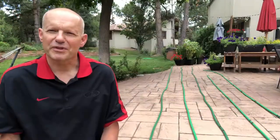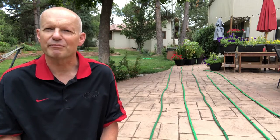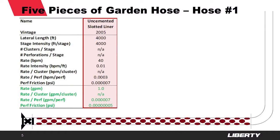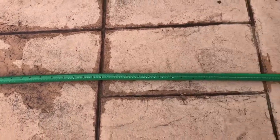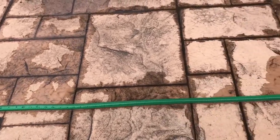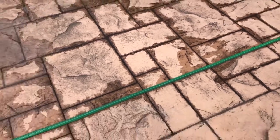So start with the first garden hose. The first garden hose represents early days of fracking, maybe even before the shale revolution. Well design number 1 is also known as pump and pray, or Hail Mary, and was not uncommon in horizontal wells before the shale revolution. In this strategy, the whole lateral is treated at once. Even scaled to my garden hose, the interval to be treated is thousands of inches in length, and the job doesn't even cover the first 200 inches.